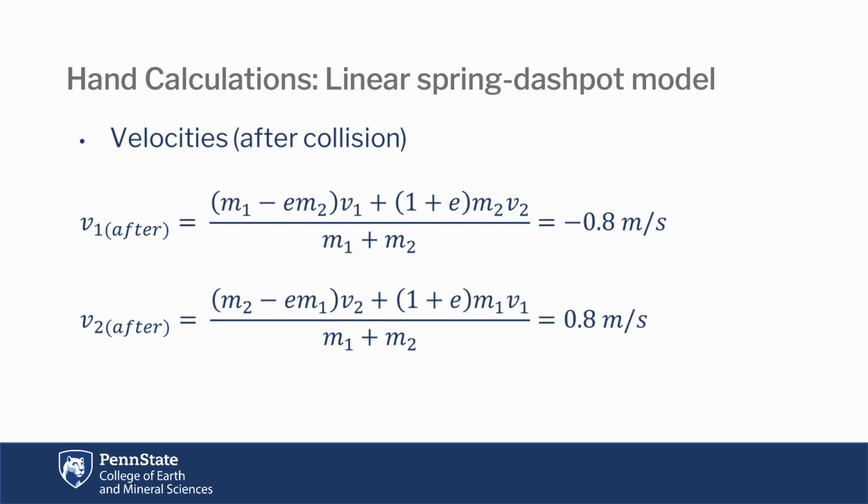And these are the velocities after collision. They are mostly a function of the coefficient of restitution. It's like saying 0.8 times the velocities in either direction, as we had earlier. And our analytical method is actually logical from Newton's laws of motion. So these are the velocities of ball 1 and ball 2 after the contact, when they go apart.